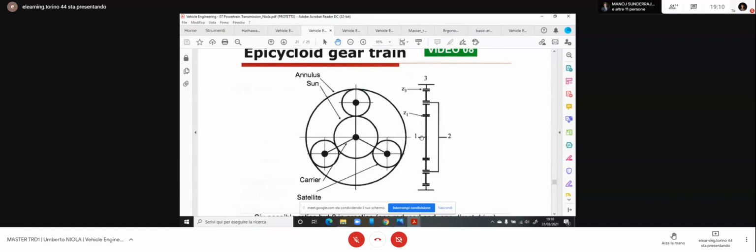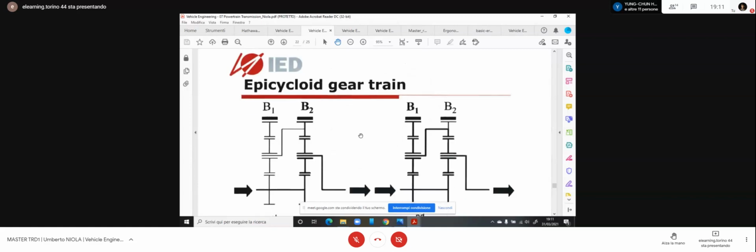You know, they are an organization of a central gear, peripheral rolling gears, and an external crown with inner teeth. So you can have different output speeds simply by braking, in terms of stopping, the rotation of this external part or the internal part. You can realize the movement of different gears.